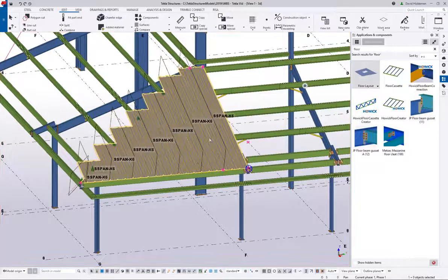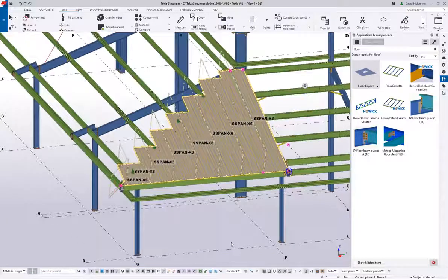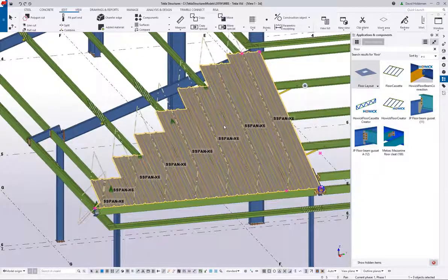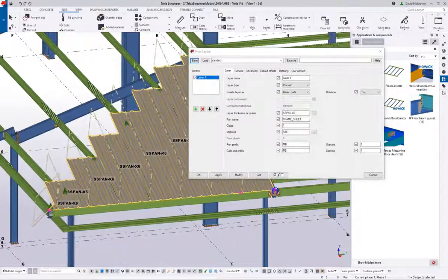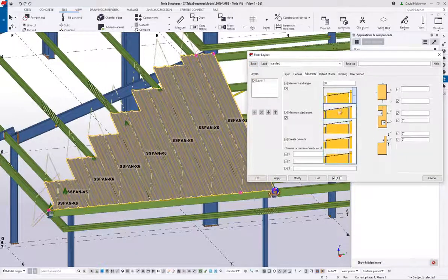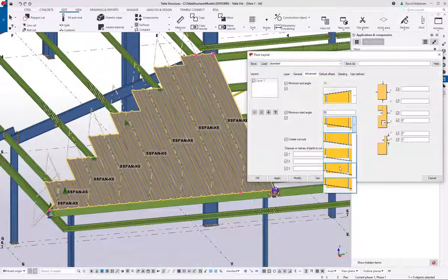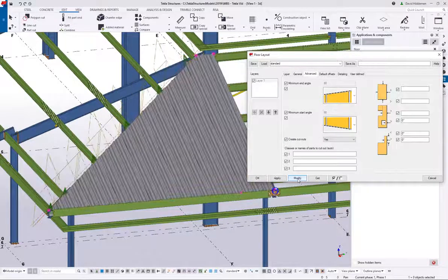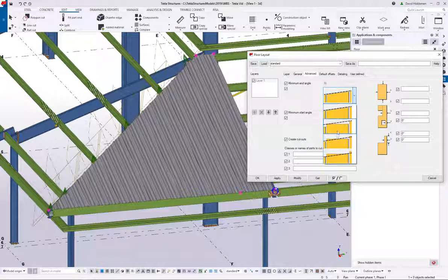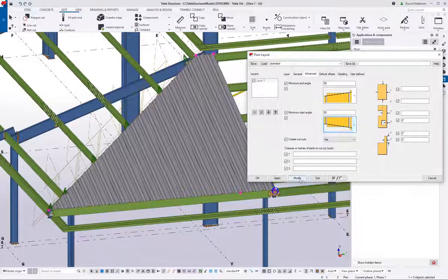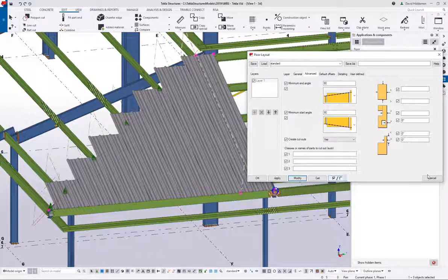Now, as you can see, the settings I'm using right now are again square cutting or giving the rough lengths of these sheets. But this tool does have the option inside, if you go to the Advanced tab, to change this up to give you again more of that field cut or finish cut look. Again, it comes down to what you're trying to represent in the model space. I'm going to go ahead and change that back to their square cut just so everything matches, and then I want to show you something else that's neat about this tool.